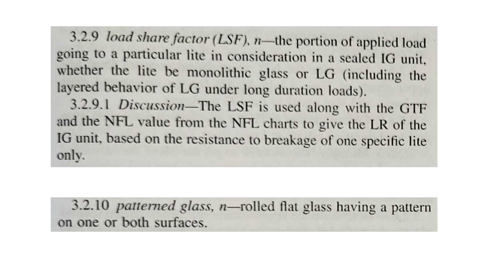So you've got a sealed insulated glass unit, and you're going to have a load share factor for one light and a load share factor for the other. Whether the light be monolithic glass or laminated glass, including the layered behavior of laminated glass under long duration load. So you've got two different panels, and there's going to be a load share factor right there.